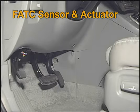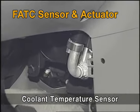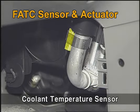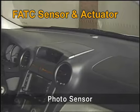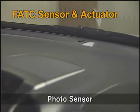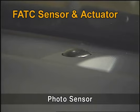The coolant temperature sensor is installed at the coolant pipe of the heater core. It sends the input signal for controlling the heater. The photo sensor is installed at the center of the instrument panel. It is integrated with the luminescence sensor for controlling the auto light.